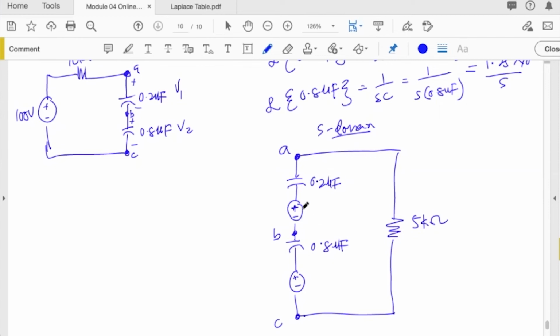So another 80%, it's like 80 volts, will be stored inside each initial condition. Okay, so that would be for our first V1s. All right, so it means we have 80 volts as the initial value provided by this initial voltage, and another 20% will be stored inside this capacitor.